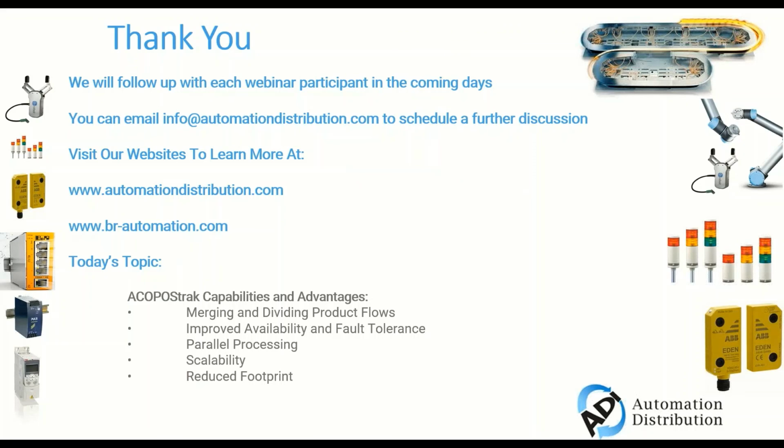They offer rapid change of line, reducing downtime. The shuttles are hot swappable. It's a dynamic system that can be expanded or shrunk to meet variable demand in production. There's a reduced footprint versus traditional conveyance, and integrated collision avoidance. And B&R has a fantastic digital twin simulation tool that allows you to do programming and troubleshooting before you ever hit the ground in a physical installation.